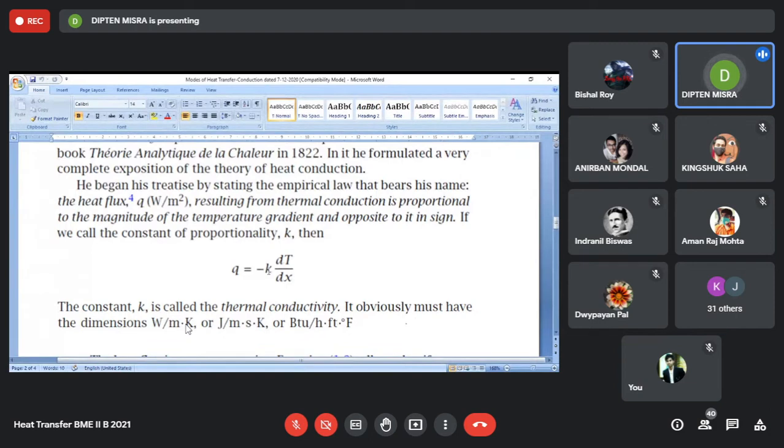One, a material property, that depends purely on the type of material that you are discussing. It also depends on the geometric feature of the body, whether the wall is a thicker one or a thinner one. That will dictate the temperature gradient. And also something external to the property of the body, something external to the geometry of the body, that determines the rate of heat transfer.